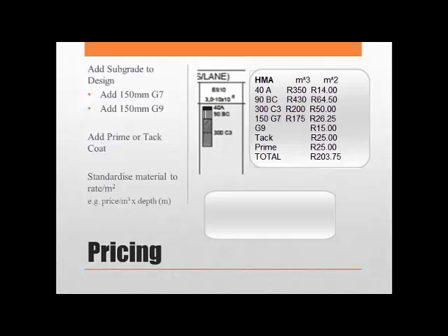However, should the cost be considered for the analysis period, the maintenance and rehabilitation would have to be considered as well as escalation thereon. If we are evaluating different catalogs and we're putting the same wearing course down, then the most critical layers really become the base course and the subgrade base, because remember, we are assuming the same subgrade for each and every design.